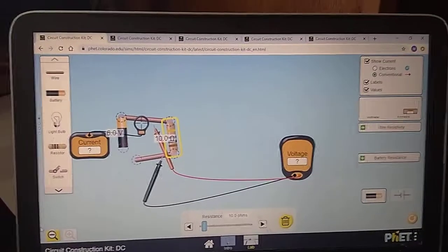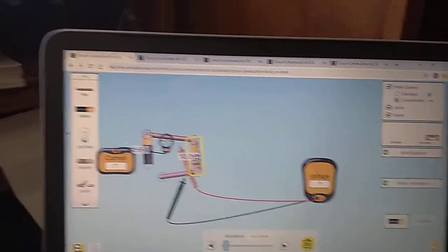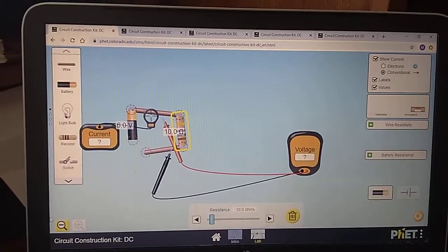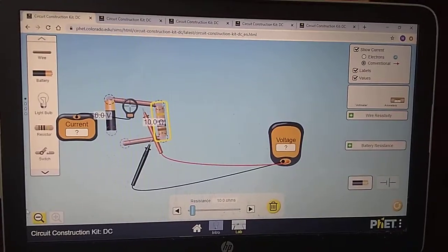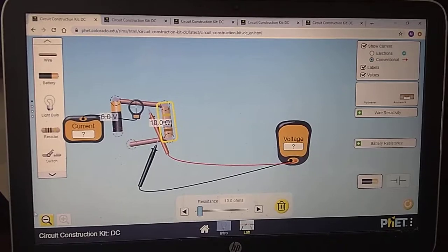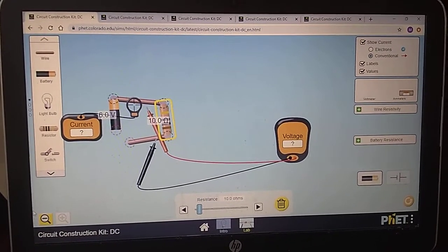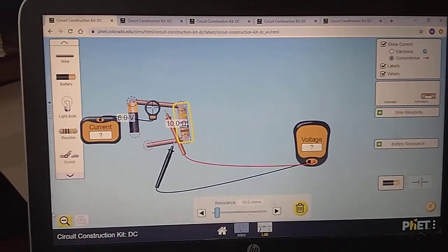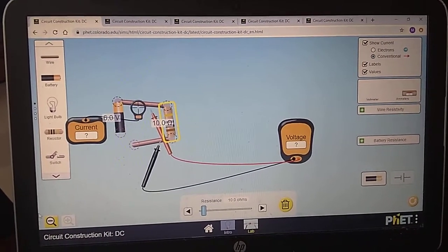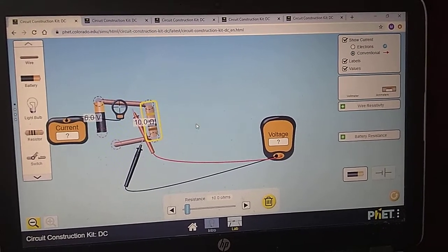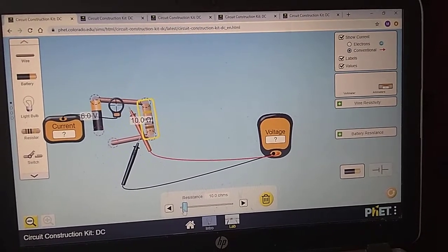Now the tricky thing with our simulations is the resistances, unfortunately, don't go all the way up into the hundreds like we want. They stop at 120. But we can still get an idea to see if this is right or not. If we can't get the full resistance, why don't we instead just use maybe a tenth of that resistance? So we got the resistance to be 300. A tenth of 300, this should be very easy for you to do, is 30. So let's make the resistance of this resistor 30.